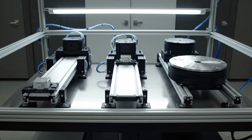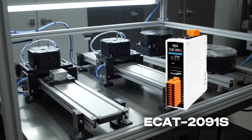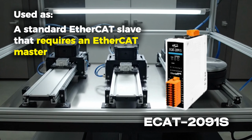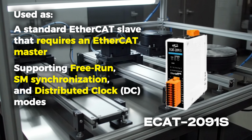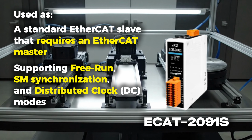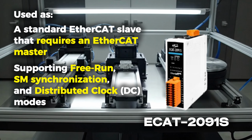So for example, the ECAT 2091S stepper motor controller is explicitly used as a standard EtherCAT slave that requires an EtherCAT master, and it supports free run, SM synchronization, and distributed clock modes. So if you're looking to build a motion application where timing and repeatability matter, a device like the ECAT 2091S is designed to operate with those EtherCAT synchronization modes.